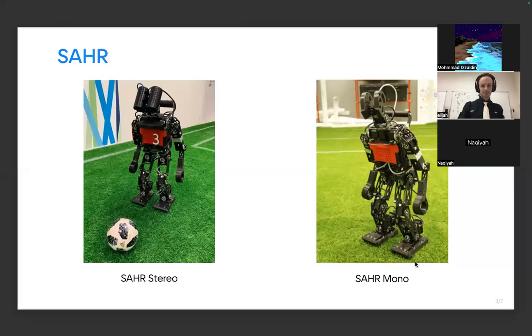That's interesting. And apart from the vision, it has the following sensors. It has pressure sensors on the feet. So when the robot is standing on the ground, it can find out if the pressure on a certain part of the foot is missing. So if the robot has inclined, he can detect that. Also, he has an inertial measurement unit, IMU.